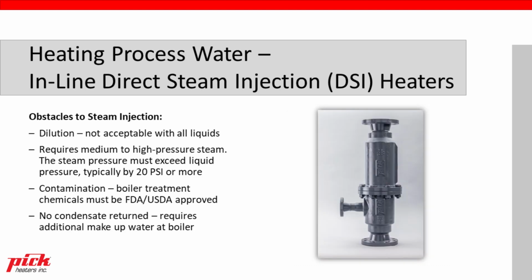There are, of course, obstacles or disadvantages to steam injection. First one being dilution. You are condensing that steam right into the water or liquid being heated, and sometimes that's not acceptable for all liquids. If there's oils or food products or certain other chemicals or pharmaceuticals where you cannot dilute them, obviously steam injection would not be a good choice here.